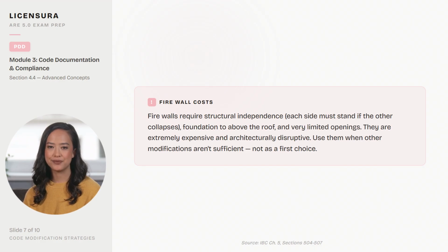Firewall costs: firewalls require structural independence. Each side must stand if the other collapses. Foundation to above the roof, and very limited openings. They are extremely expensive and architecturally disruptive. Use them when other modifications aren't sufficient, not as a first choice.